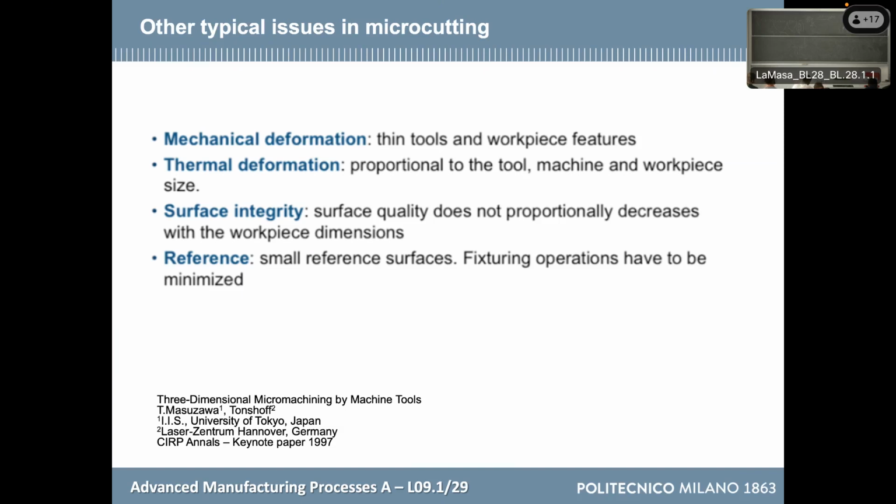Surface integrity is roughness, in other words. In roughness and other things like residual stresses, everything is happening at the surface. Also here, we cannot scale down everything. So at a certain point, we have side effects. For example, we have talked today about plowing. Plowing is getting a worse surface. So if I want to obtain a nice surface, I have to switch to other solutions, like I have said, a diamond tool, which is really sharp. Otherwise, I cannot get the job done.